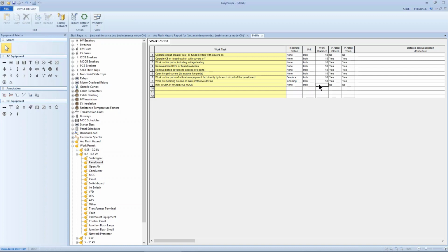accordingly. Now there's another point I want to emphasize here, and that is if I'm going to be putting on special conditions, and I know the procedure requires something other than the calculations for the bus itself, then I need to make that condition part of the description. So that's what I'm talking about. So again, I'd apply this to both MCCs and probably my panels. Let's go ahead and put another one on here in case I...